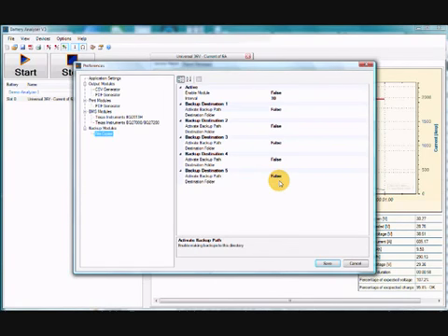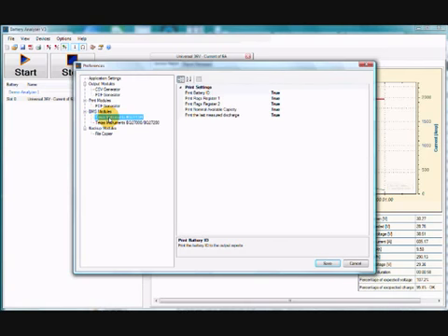A battery pack may contain a BMS, a battery management system, with external connections for readout. The BA500 can read HDQ and I2C, and a number of BMS chips are supported. In Options and then Preferences, and then go to BMS Modules, the readout of the chips can be configured. As you can see, different chips have different features. The BQ2013 has 5 values. The enabled values will be printed on the output report.